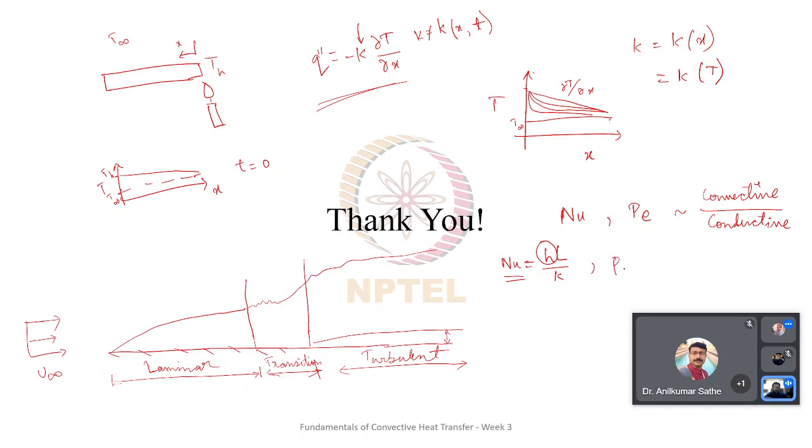On the other hand, Peclet number is also similar to this, but Peclet number is actually a class of dimensionless numbers. We study Peclet number with respect to heat convection only, or with respect to heat transfer only. But Peclet number has other uses in mass transfer, mass diffusion, and advection as well.